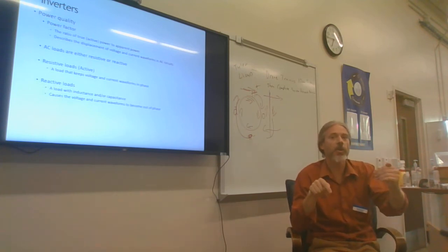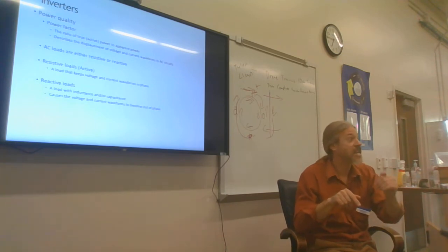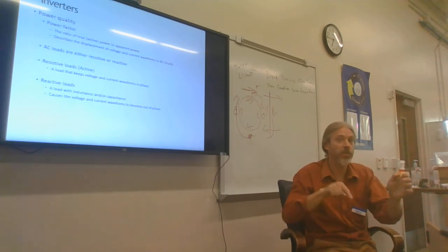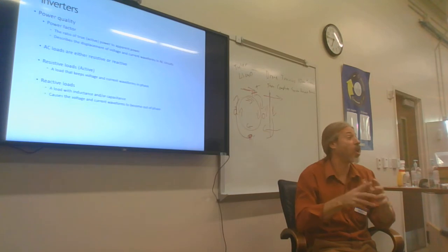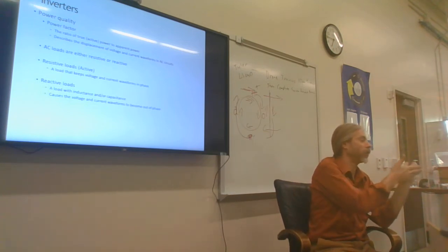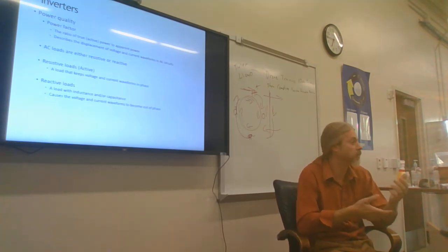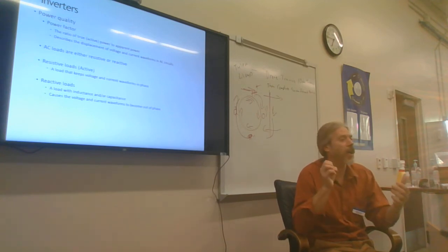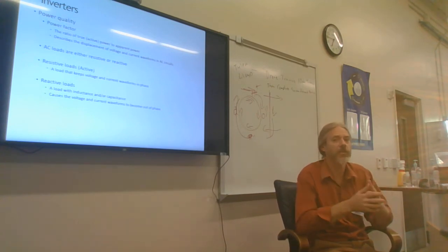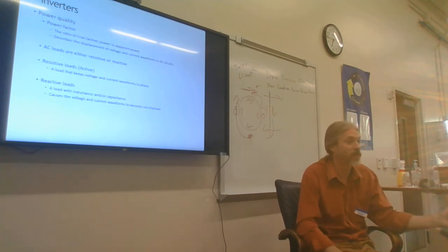All right. So if I have an inductive load, I need to have a sinusoidal waveform, or else I'm going to have a whole lot of wasted, not true power. Okay. That wasted power is going to show up as heat, and it could potentially damage appliances, motors, and even have signal interference, like keeps your radio from being able to pick up the proper signal.